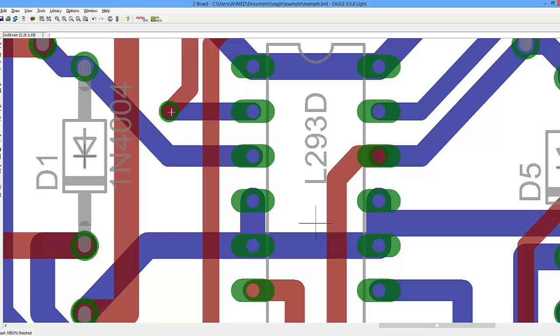There is some strange equation inside Eagle that I don't know about. I tried reading about it, but I couldn't reach a conclusion on how to control it. I know somebody will scream at me and tell me it's done like this, you idiot, but either way, for this one, there is no other way than to modify it. You have to modify the via width itself.